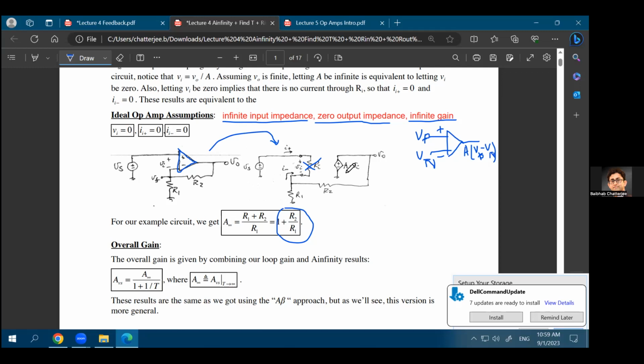Okay. Now, with this circuit, you can do a KCL and KVL based analysis, and then you'll come up with this particular equation. And while doing so, it is usually assumed that for an amplifier you have a property called a virtual ground. What the property called a virtual ground means is that if you ground, let's say, this negative terminal, the AC fluctuations, or the small signal fluctuations, on the other terminal will also be equal to 0.